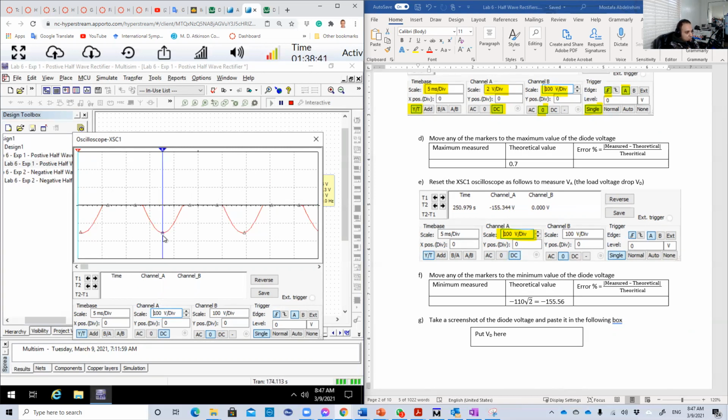Which is the constant voltage model, of course. But if we use the ideal model, it should give you very accurate results, because the 0.7 clipping is really very small compared to the minimum voltage. As you see here, it's not noticeable at all. We cannot observe it at all. So this is all for the VA or VD.